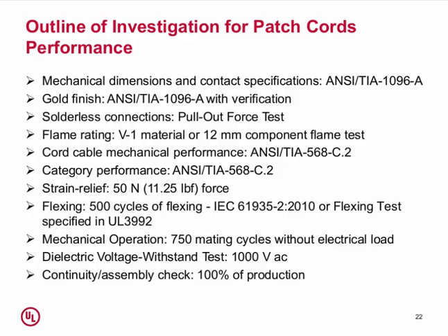This is strictly a physical mechanical test. Dielectric voltage withstand test of 1,000 volts AC between the pins and between the pins and any grounded or shielding that might be associated with the jack. And then the standard also requires a continuity assembly check on 100% of production.